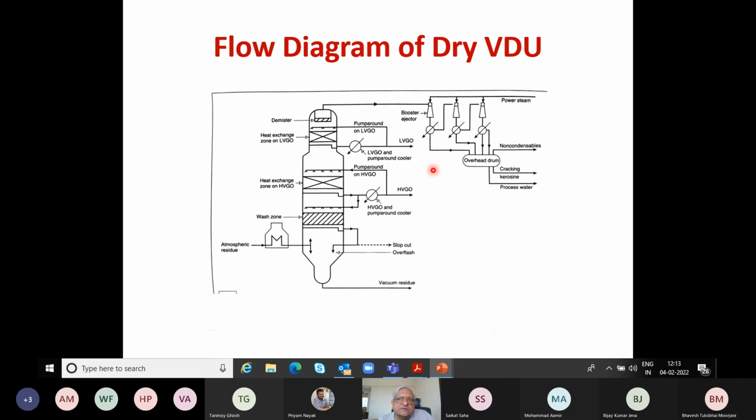You can work out this calculation that if you have a pipe of length 10 meters, and the pipe top is exposed to atmospheric pressure, then the bottom of the pipe would have 1 kg per square centimeter pressure. That is H rho g by gc, so height into density.